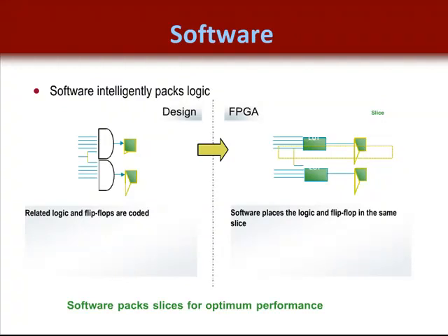The Xilinx implementation tools, commonly called the place and route tools, take the synthesized design and map the logic to the FPGA resources. In this example, this is simply a gate to LUT exchange. So while you will code an HDL with a gate functionality, it is the synthesis tool's job to build a design netlist that includes Xilinx primitives, that is, LUTs, registers, and other resources. The map program, part of the implementation process within the implementation tools, will then group the resources into slices, effectively for speed and maximum device utilization.